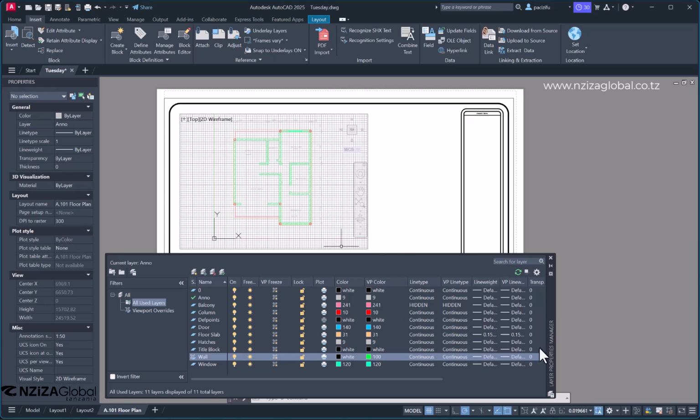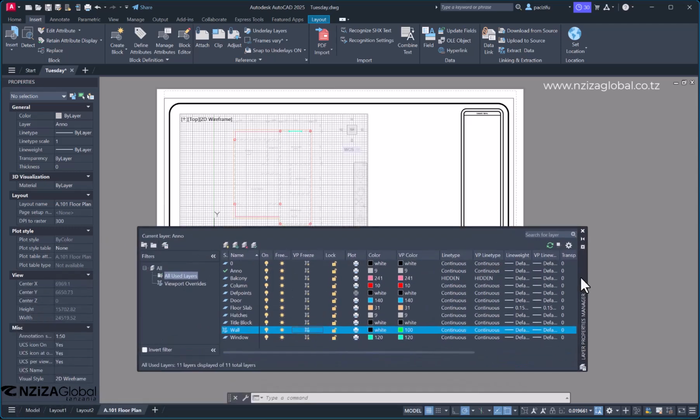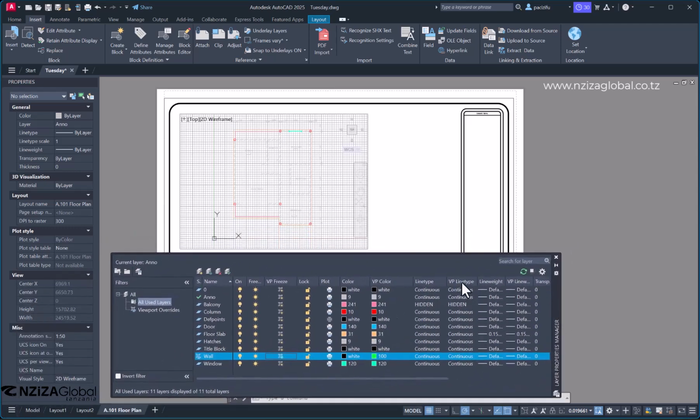You may use this kind of control using layers. This goes for the colors and for the visibilities. You can even freeze them so that they do not appear on the drawing, but on the other drawings they remain there. So for the line type, maybe the same.